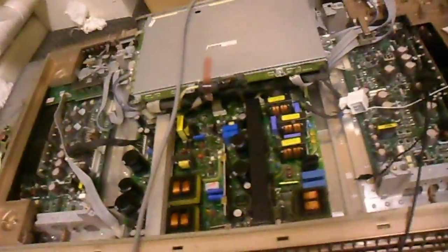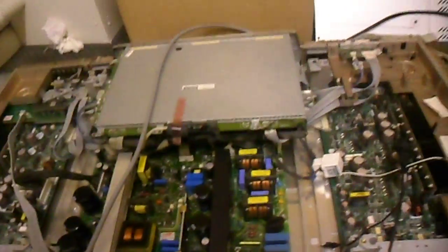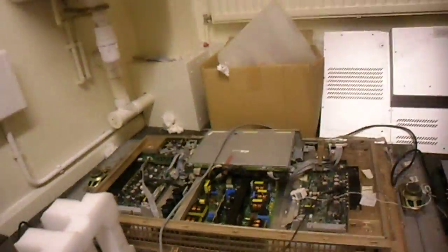The other build quality, it's got very high capacitance. You'll need to be very careful. I mean, this is only 83 volts, which will probably still kill you, but it's not half as bad as a 200 volt sustain. So just be very careful. Don't touch it while it's running, because you will kill yourself. And that sucks, because life is a kind of pleasant thing.